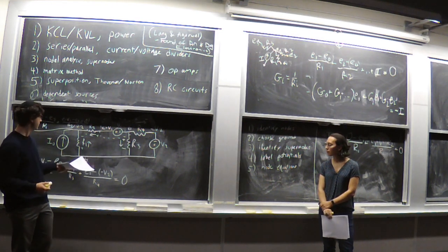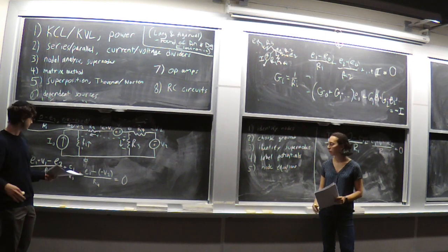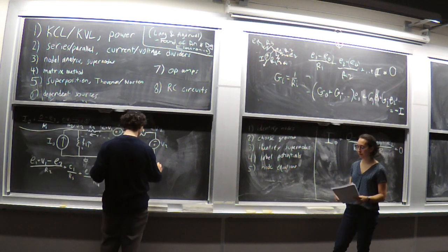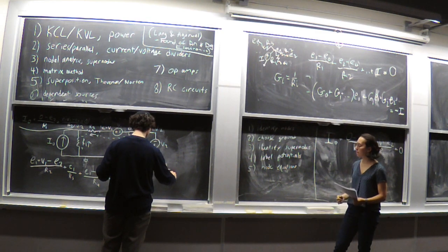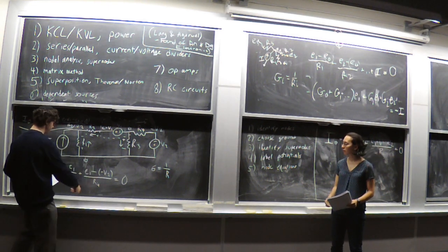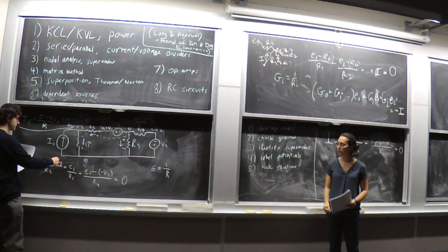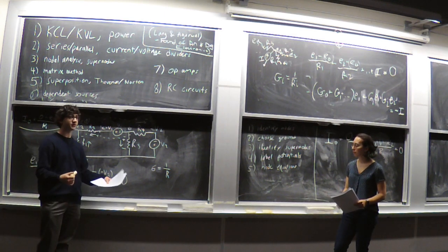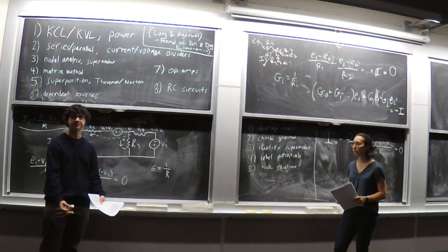As Hannah was talking about before, it's often messy to have all of these fractions, all of these terms with resistances being divided. So oftentimes it becomes easier to talk about the fact that the conductance equals 1 over the resistance. We could replace over R4 with just times G4, and this would turn into E1 times G3. This would be E1 plus V1 minus E2 all times G2. That would allow you to write an equation with no fractions, which could then be put into a large matrix that would describe the entire nodal analysis of the circuit.